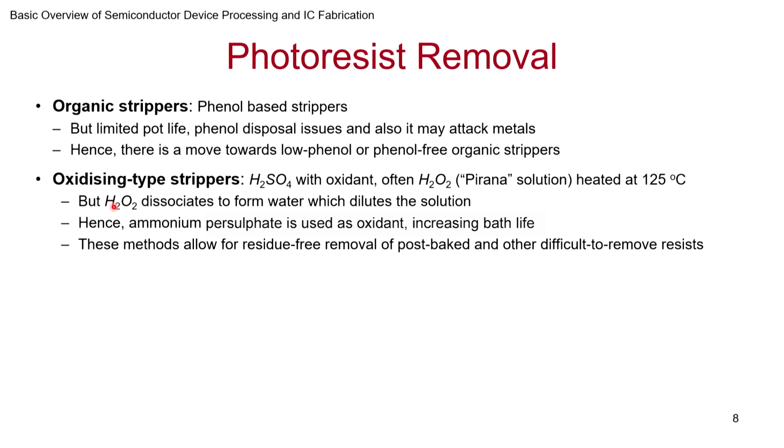Okay, but when you use H2O2, the byproduct is H2O. When it oxidizes, it gives one of the oxygen atoms and becomes H2O. That means with time the solution becomes more and more dilute. So you have to keep replenishing more often. It can be done, but it's an additional pain. So what people are moving towards is ammonium persulfate, where you don't have water as a byproduct, and so the oxidant, when it's used that way, increases the bath life. You have to change the solution not so often as you might have to do if you had used H2O2.